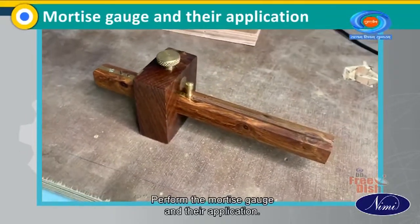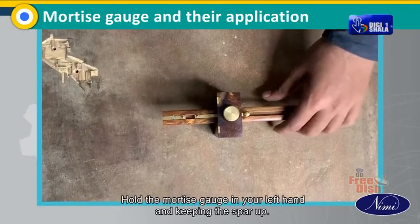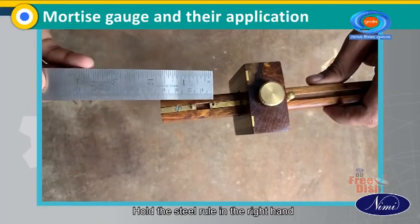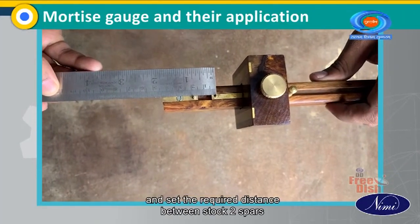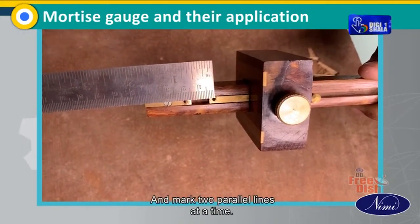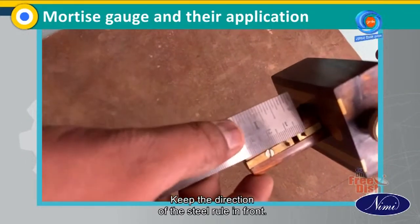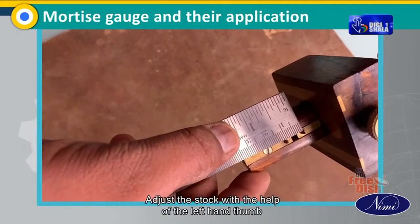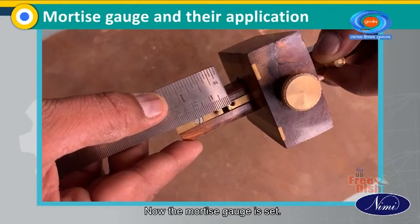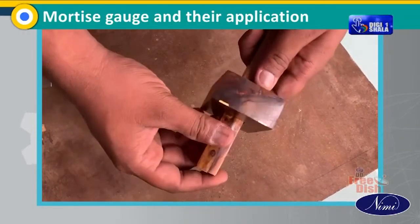Task 2. Perform the Mortise gauge and their application. Hold the Mortise gauge in your left hand keeping the spur up. Hold the steel rule in the right hand and set the required distance between stock and spurs. 2 spurs can be spaced at different distances and mark 2 parallel lines at a time. Keep the direction of the steel rule in front. Adjust the stock with the help of the left hand thumb and index finger. Now the Mortise gauge is set. Tighten the thumb screw to fix it in place.